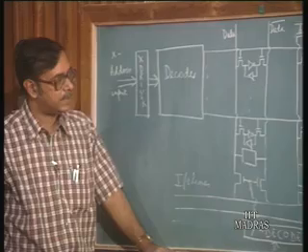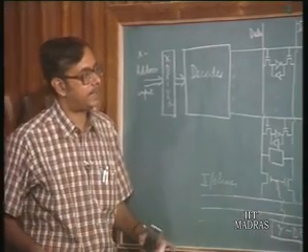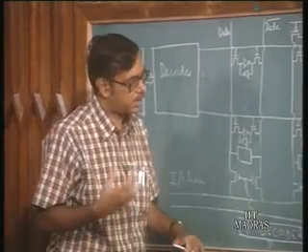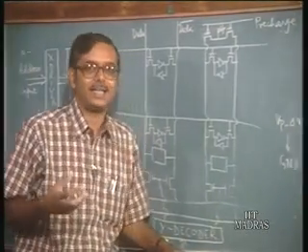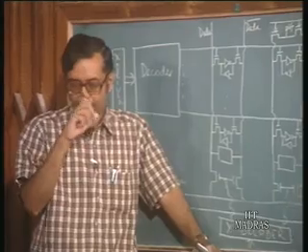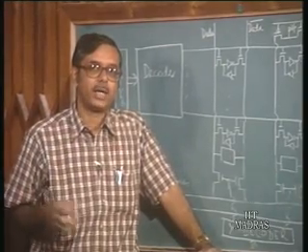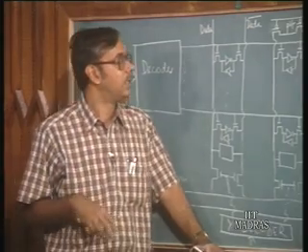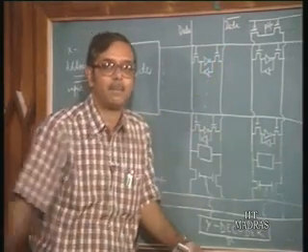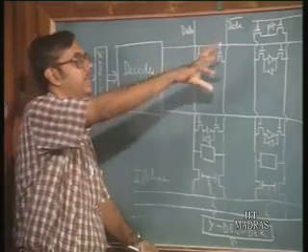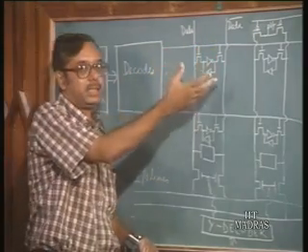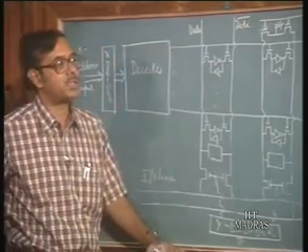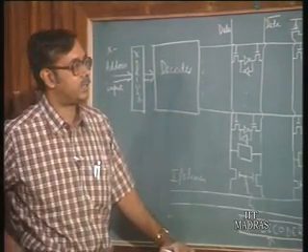Now, we have already seen that BiCMOS has certain advantages over CMOS, especially in the area of driving large capacitive loads. We have seen as an example that the word line has a large capacitance, and so, for example, BiCMOS can be used to drive these large word lines.